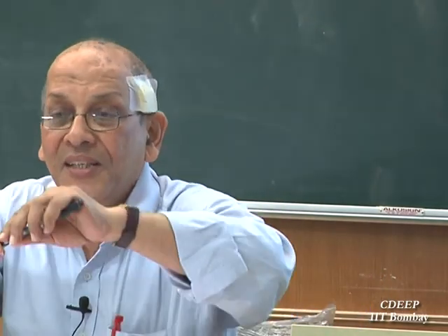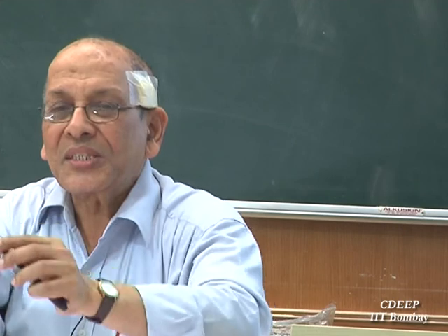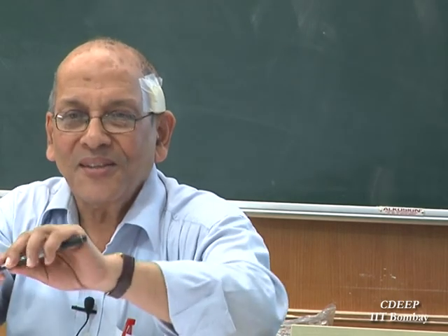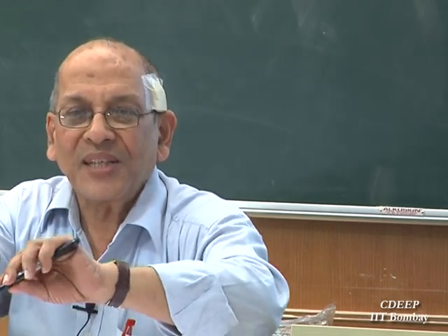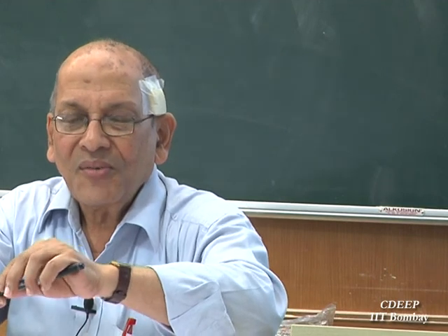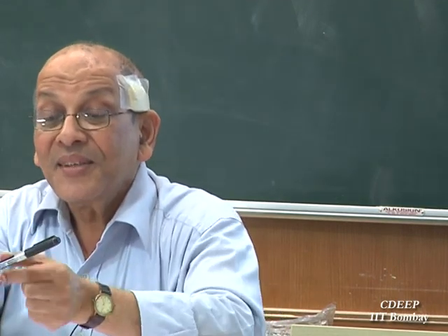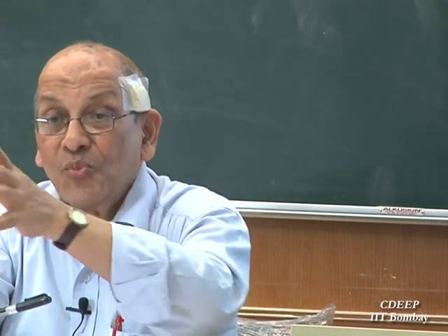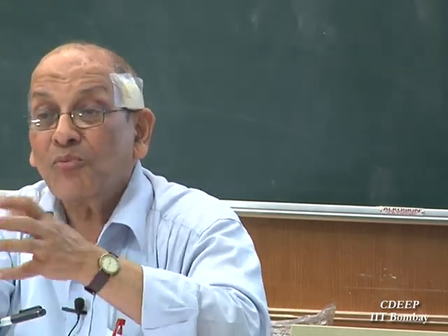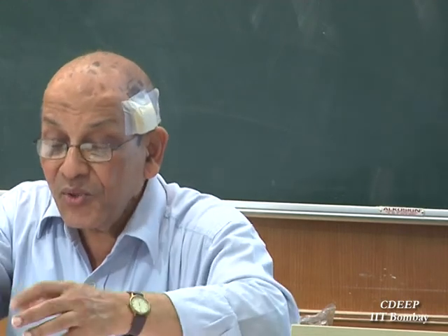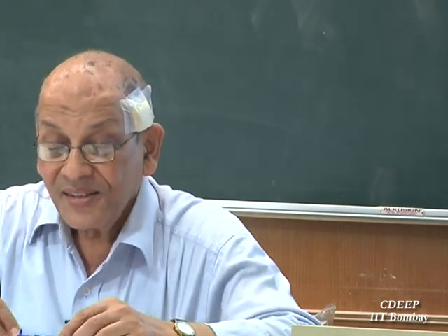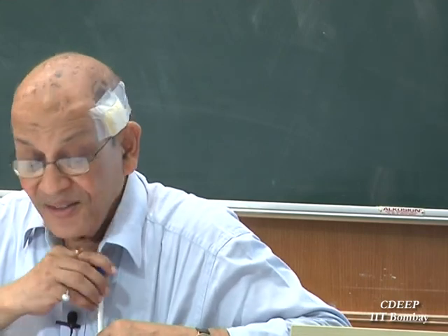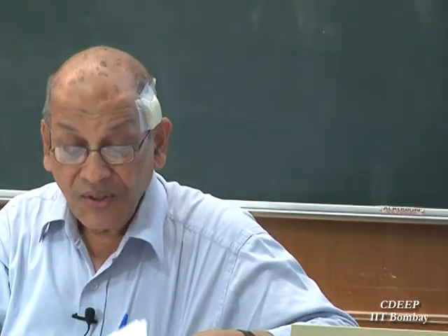Here it is a plastic hinge, which can rotate freely because the material has become fully plastic. But at the plastic hinge, there is a moment acting because the stress diagram is there. So the moment is constant, and that moment is called plastic moment. I will tell you about this in the next class on Monday.